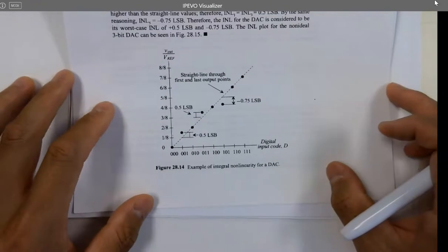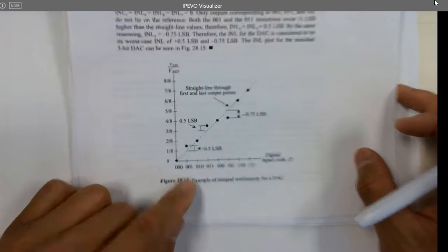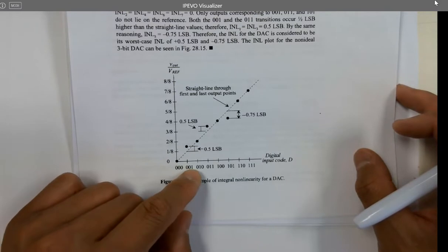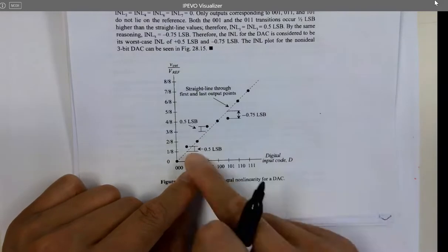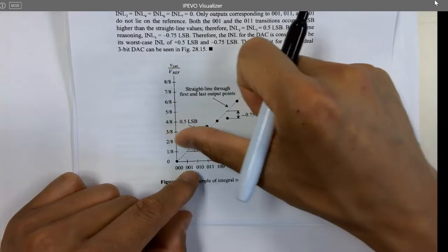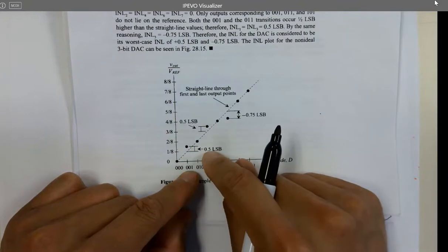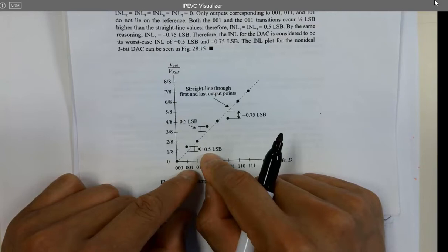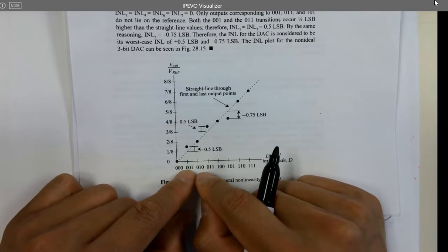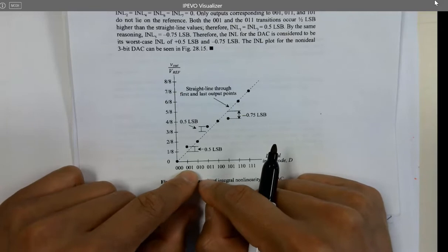Look at here. For INLs, do we have any INL for 0? No? What about INL 1? Look at the absolute value here. You are using the y value of this point, minus whatever is on the ideal curve. I already labeled that difference for you. For the subtraction, you are expecting 0.5 LSB. So INL 1 equals what?